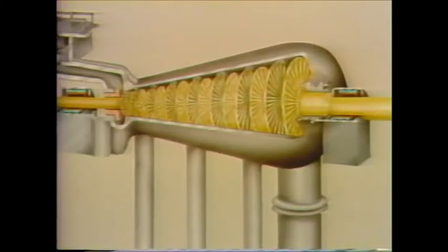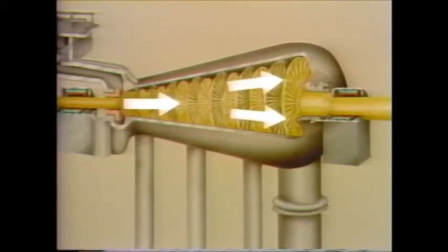In another turbine design, the sections are connected to different shafts. In this example, the HP and LP sections are on one shaft, and the IP section is on another shaft. This arrangement is called cross-compounding. Now, while each section in both types of turbines we've mentioned works in the way we've just described, they are not totally identical. For example, the wheels, diaphragms, and blades of each turbine section get larger as we move from high to low pressure. By the time steam has traveled this distance, its volume may increase as much as 150 times.